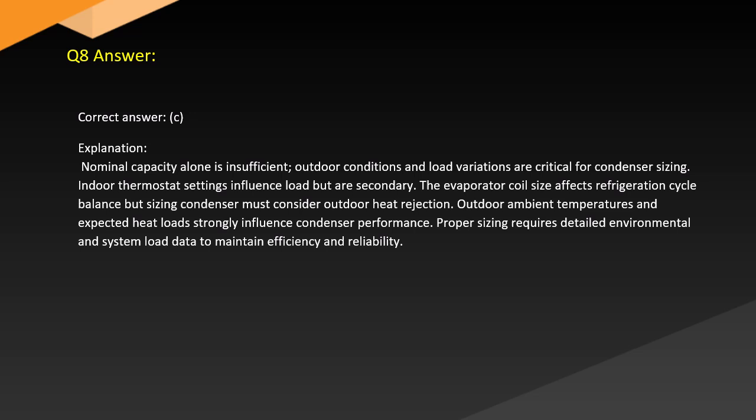The evaporator coil size affects refrigeration cycle balance, but sizing a condenser must consider outdoor heat rejection. Outdoor ambient temperatures and expected heat loads strongly influence condenser performance. Proper sizing requires detailed environmental and system load data to maintain efficiency and reliability.